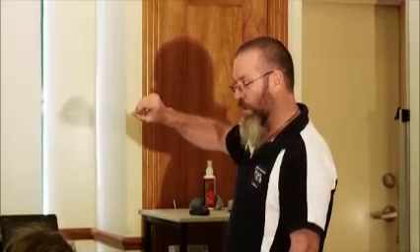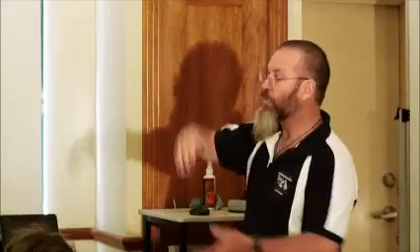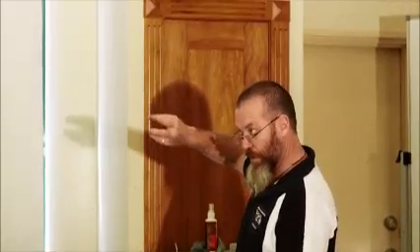And I'm sorry, I haven't got any better way than explaining that to you. If, say, you were doing a lintel connection, a lintel to the stud which is actually connected to the plate, which we'll have a look at in a minute, you select it from that second row. If you're doing your plate to your first floor, it says single or upper story, your upper story bottom plate to the floor frame, you get it out of that third row.